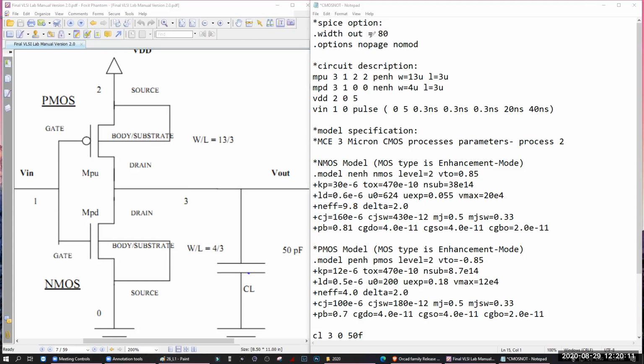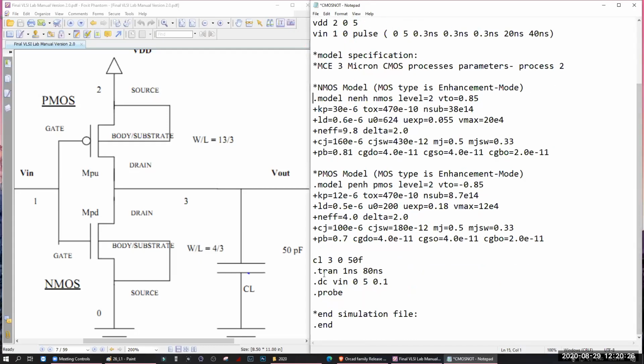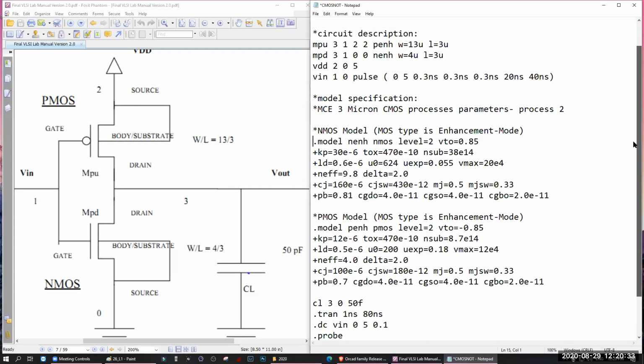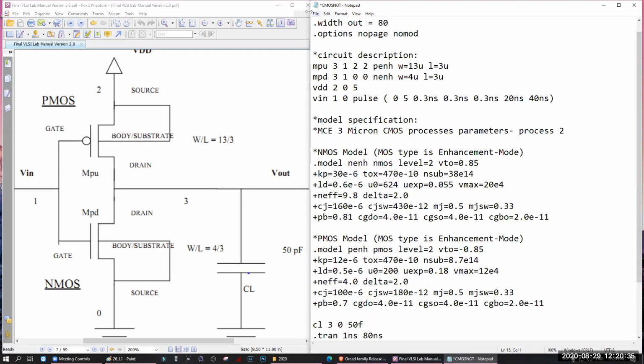Now, when you start the code using a dot, dot means operation. So see this one. When you give .tran, .end, .probe, these are operations. When you give a dot, it will be taken as an operation. Now, when you start a line with plus, that is the specification. When you write the specification, you give plus. Here you are giving plus.